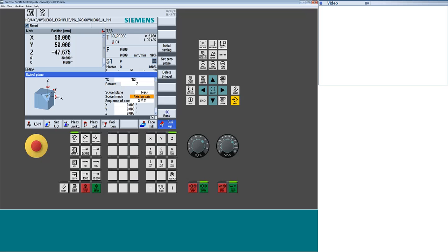Well, there is no B. So you as a programmer would have to know, well, I got to spin my platter around 90 degrees to make my Y now really relative to my X, so I can then spin it around the A. So I would have to do C of 90 and then an A of 45. Well, that starts to get pretty complicated as I start to think about these things.